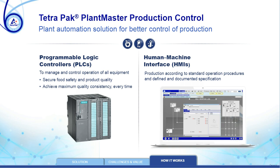From this place, the operator can control and operate the plant in production, according to standard operating procedures and defined and documented specifications. But the PLC is where your program is running, so where the process logic actually sits. The PLC acquires real-time information on the process parameters, and the PLC also issues appropriate commands to the equipment on what to do, whether a valve or pump should start, or open and close.